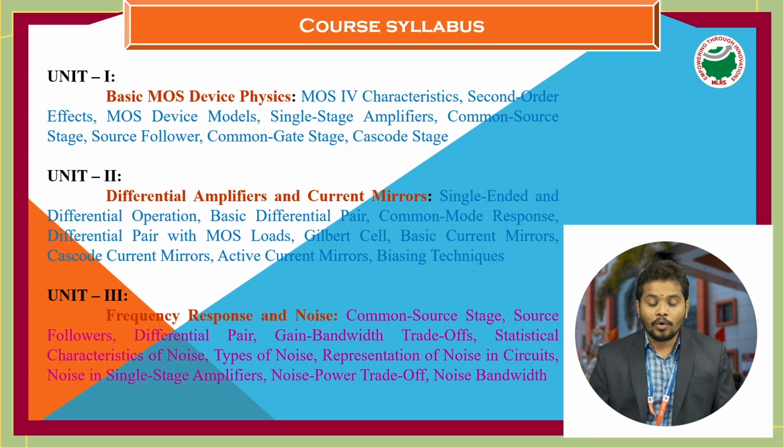After that, we have MOS device models. What is a MOS device model? We have different types of MOS device models. Before going to them, what is the use of MOS device models? By using these MOS device models, we can find the DC gain and the AC gain. The DC analysis of the circuit is also possible by using these MOS device models.